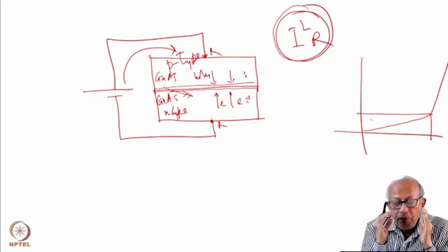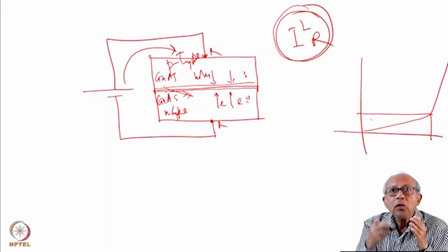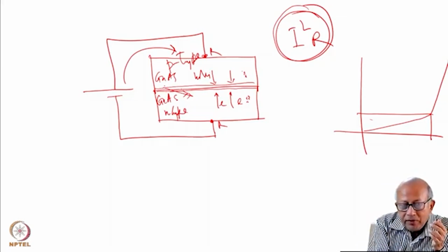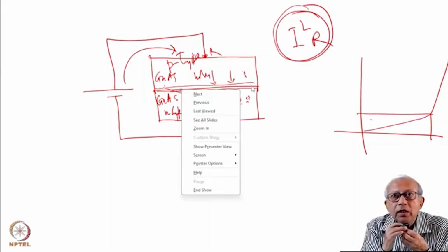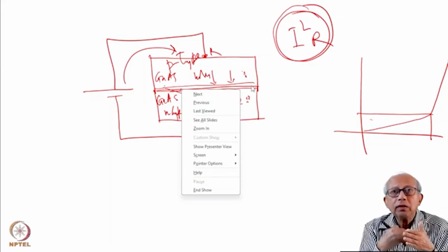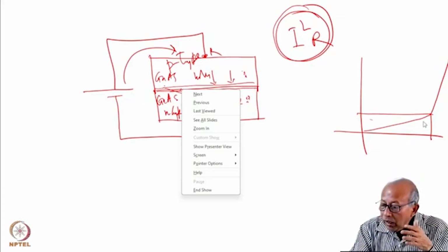So, if we can confine them, then only the threshold current will become less, because we are able to confine light, and also confinement of these charge carriers will ensure that they combine much more efficiently at a better rate. So that will reduce the threshold current.